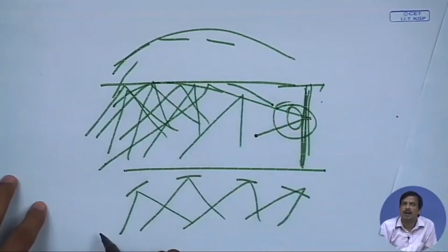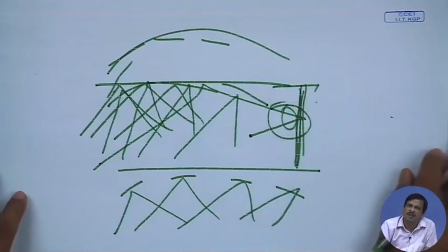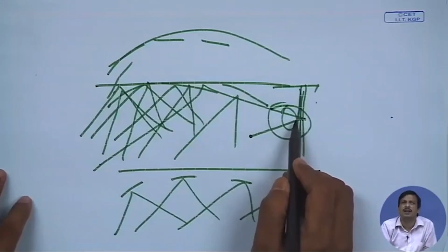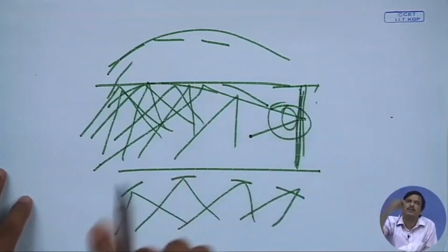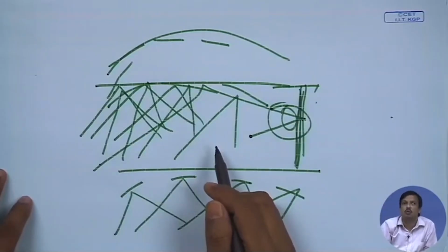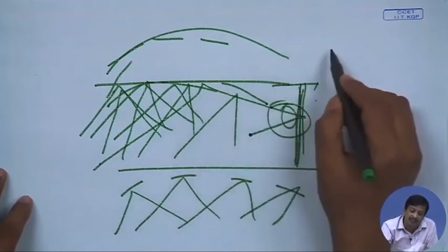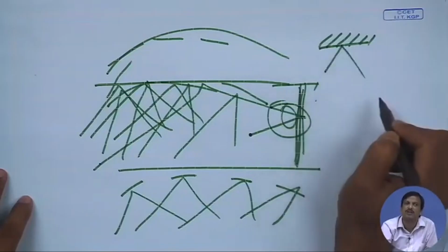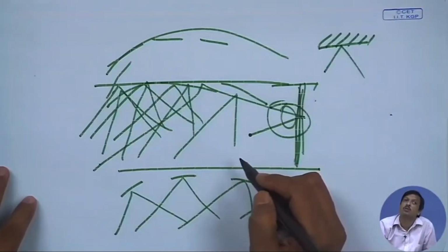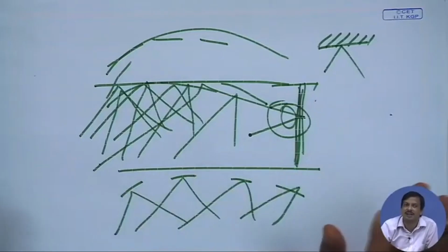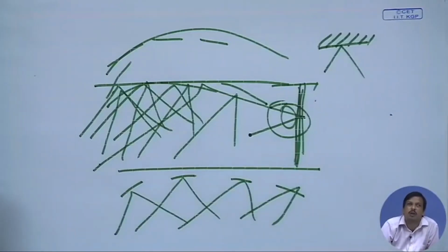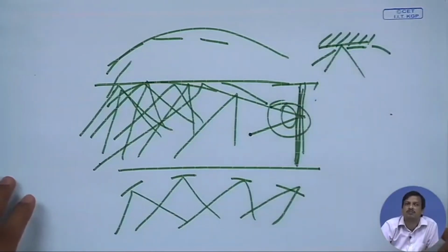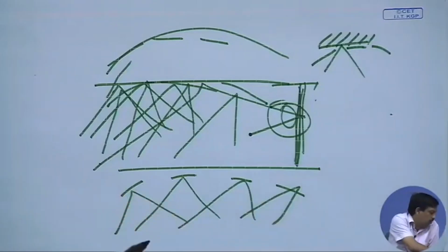Okay. Unless the ceiling height is very high, always put a reflector in the ceiling. If the ceiling height is very high, then what will happen? Reflection from the ceiling may create an echo. To avoid that echo, in that case I require a totally absorptive surface in the ceiling, so that no reflection comes from the ceiling if it is too high. If it is not that high, and there is no possibility of an echo, I can put a sound reflector there, so that it reinforces the reverberant sound. Okay. So, that kind of treatment I have to make.